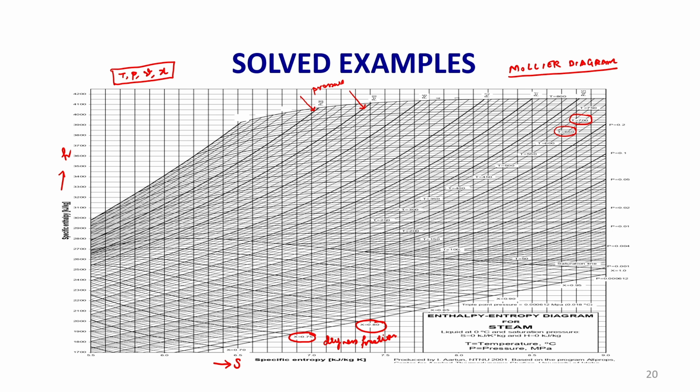Okay. So, because it is not very clear, I have just explained where the other 3 lines are. But any Mollier diagram will have these 4 lines. X axis is entropy, y axis is enthalpy. Then we have constant pressure lines, constant temperature lines, dryness fraction lines and specific volume lines in meter cube per kg. Let us see how to take the enthalpy at state point 1 and 2 directly from the chart.